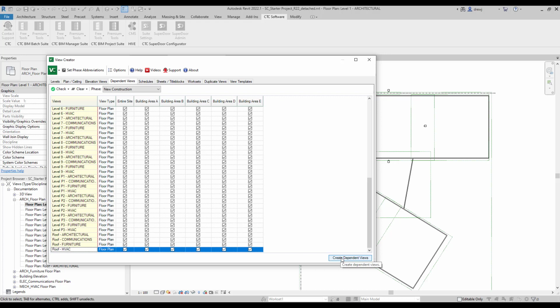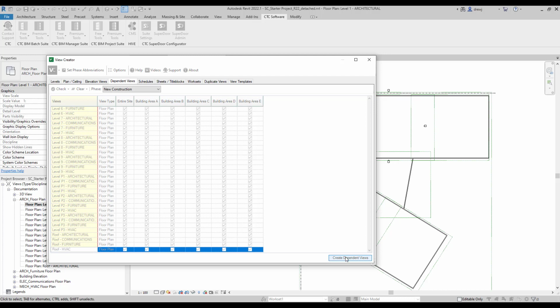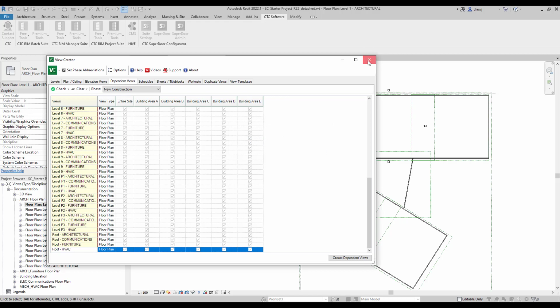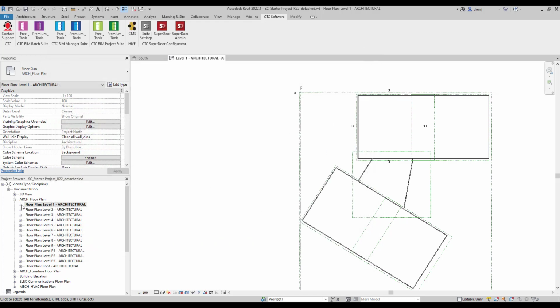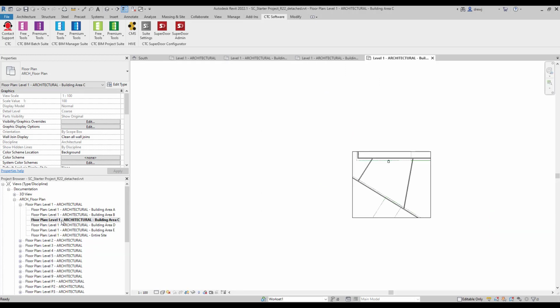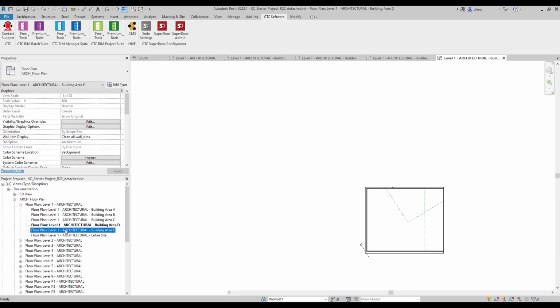So I made 52 views, was it? And now I've said I'm going to make 5 dependents for each one, 250 views. How long is that going to take you to do manually? It's going to take a few minutes, right? Let's click that button and allow it to make it for us. Okay, and because I didn't uncheck the entire site, I've now actually made too many dependent views, but we made 300 dependent views there in no time at all. Let's close that down and take a look. So we can see within the level 1 architecture, we've got our building A, building B, C, D, and E.